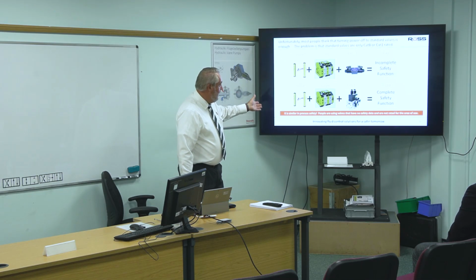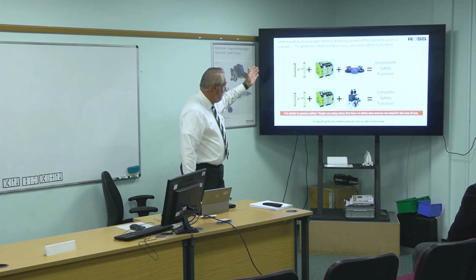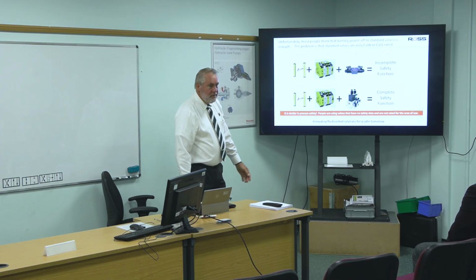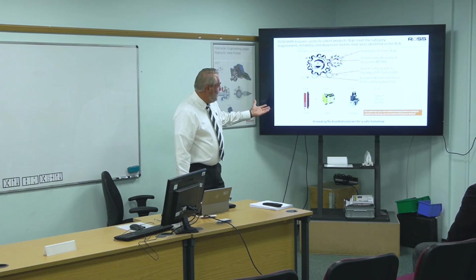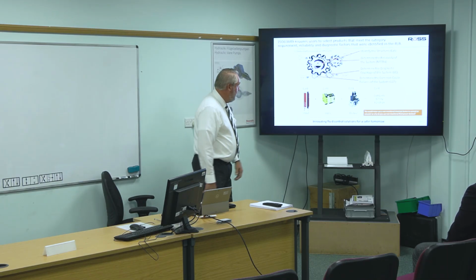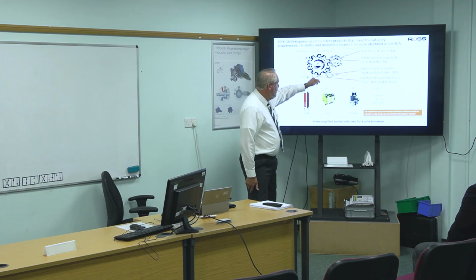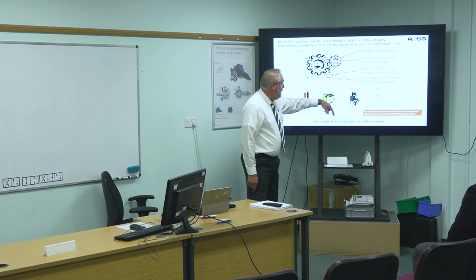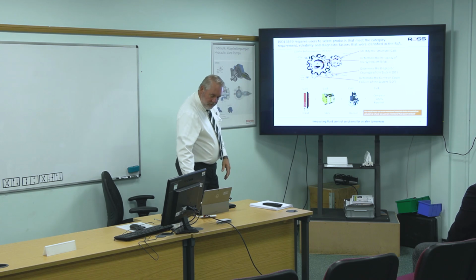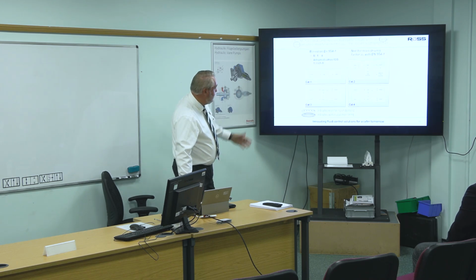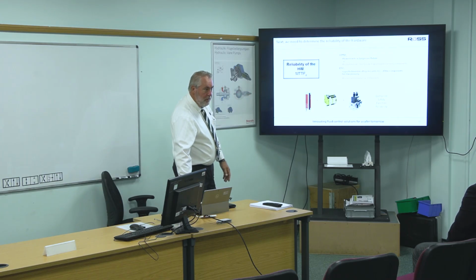And just keep in mind, all of your safety solutions are made up of input, logic, and output. When we look at machine safety, performance levels are made up of the category, reliability, and diagnostic coverage. That's what makes a performance level. What that means is I have to pick the right structure, and I have to pick hardware with the correct reliability.